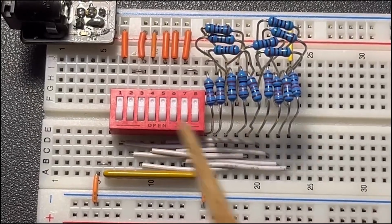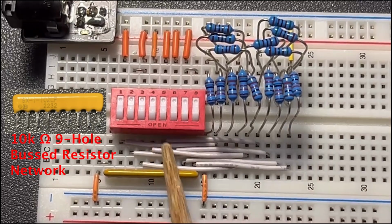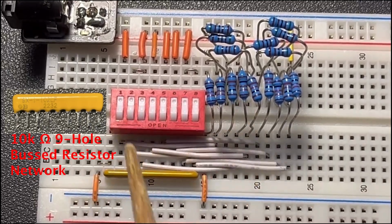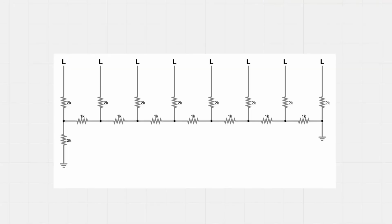So this is my R2R DAC ladder circuit. We have a switch bank here for the inputs, a resistor network connected to ground so there's no floating current, and then finally the ladder itself. This is my R2R digital to analog conversion ladder.